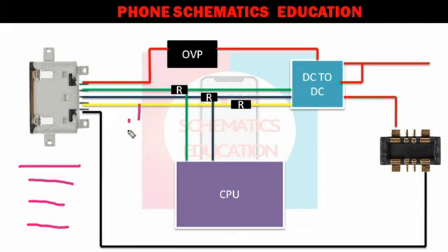On this line you will get 1.8 volt before connecting a charger or OTG of any type. But when you connect an OTG that has 4 points, this line is directly connected, or shorted, to the ground line. It means this 1.8 volt becomes 0 volt.